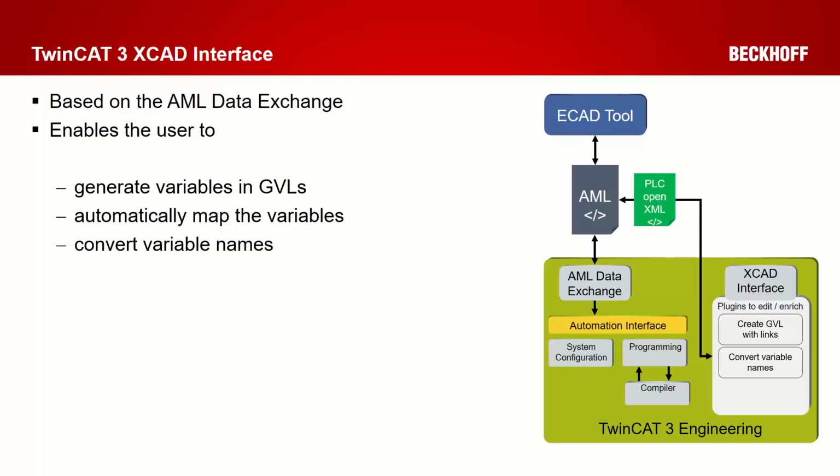In addition, the XCAD interface also allows to automatically add comments which are defined for each of the tags. So it is possible to define comments on the ECAD tool side. They are exported, and we can then import and add them automatically on the channel side, so in the I/O topology, but also for the variable which is automatically generated.